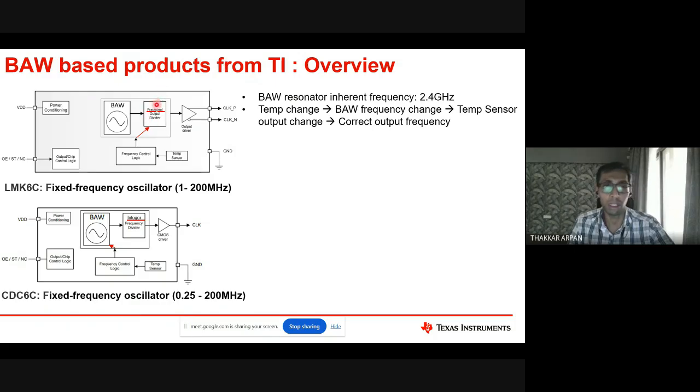But right now, these are clock sources, right? There are some parts where you can request programmability, but usually we also have fixed parts available, because some customers say, I don't want to program, I just want a clock. So they specify, let's say, I want an output frequency of 1 gigahertz, and we program the fractional divider and sell it to them. So it will always give that frequency. Those options are there. Anyways, basically this part can generate essentially any frequency possible, whatever the fractional divider supports, from 1 megahertz to 200 megahertz.